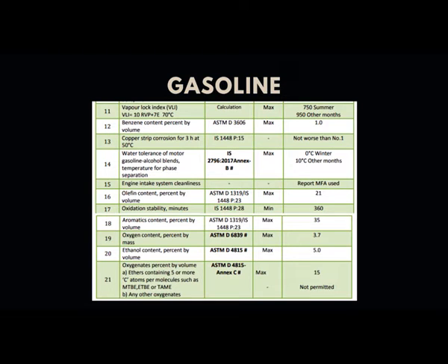Each test has some specific significance, and because of that reason, in the refinery quality control lab, whenever a batch is ready, the complete test is done. Only when the complete test is done, the laboratory will give a batch number, and it will allow the particular parcel or batch to be taken to the end customer. Even if one test is not meeting the specification, the entire batch is known as off-spec, and finally the off-spec batch needs to be reprocessed or reblended and again retested.